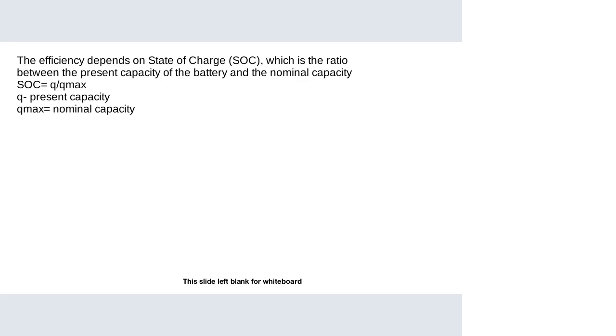These batteries are used in power generating solar systems and are actually different from car batteries. Most of the time you'll find people using normal car batteries, but those are not designed for solar systems. For a battery to be used for a PV system, it should be able to withstand high, deep charging and discharging cycles without degrading too much. That's why there are specific types of batteries that are used, which include the lead acid, the lithium, etc. Car batteries are not meant to withstand those high charging and discharging cycles.